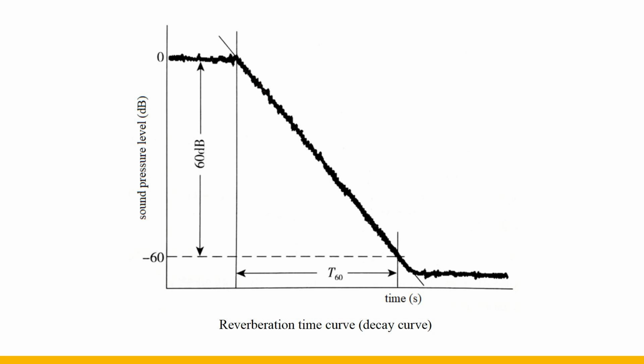Reverberation refers to the residual sound phenomenon formed by the late reflected sound from various interfaces in the sound field after the sound source stops sounding. The reverberation time is used to characterize the length of this phenomenon. Sabine defined the time that the sound takes to decay by 60 decibels from the steady state sound pressure level as the reverberation time after the sound source stops sounding.